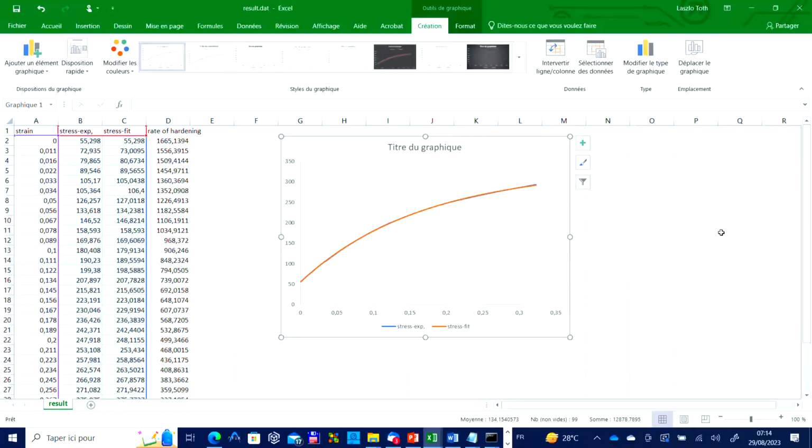It's important. This is true stress, true strain. True plasticity and true stress, that is the input. True strain, you know, corrected for the section, and it's not the engineering stress and strain. For that, it is not working. It has to be true stress, true strain. Very important. You are also getting the rate of hardening as an additional output. Yeah, it is there. You can plot it, but that should be plotted in the Kocks-Mecking plot, the rate as a function of stress. You can do that.